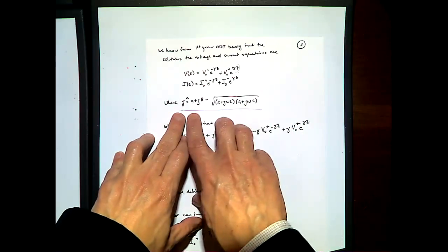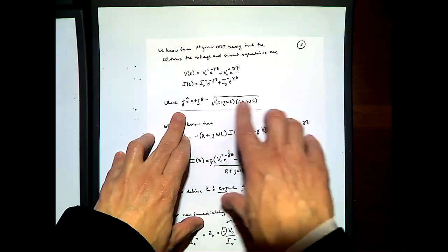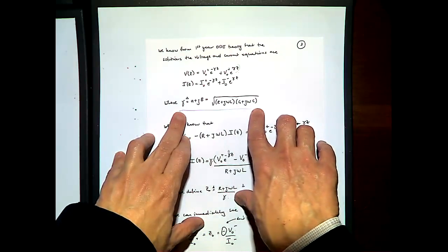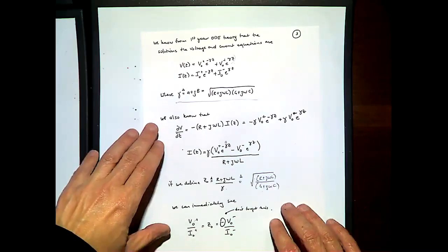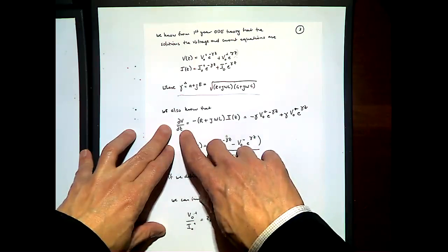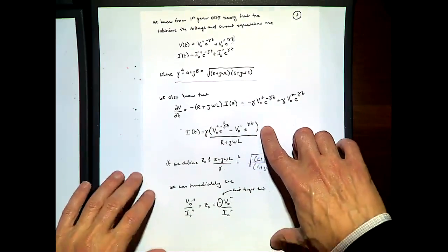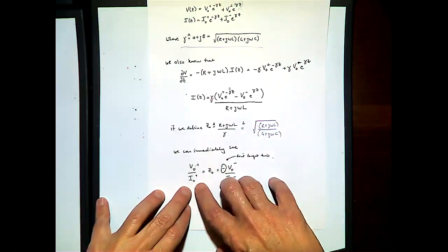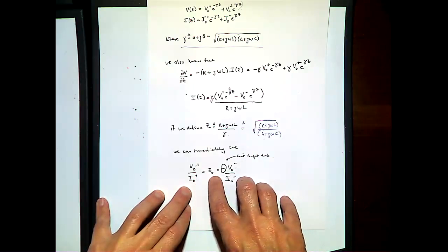Transmission line, and essentially it tells us how a wave travels along this transmission line in terms of these fundamental components or characteristics of the line. Likewise, we differentiated the voltage with respect to distance along the transmission line, and we worked out the current. And most importantly, we defined the relationship of the positive going voltage wave to the positive going current wave as the characteristic impedance.